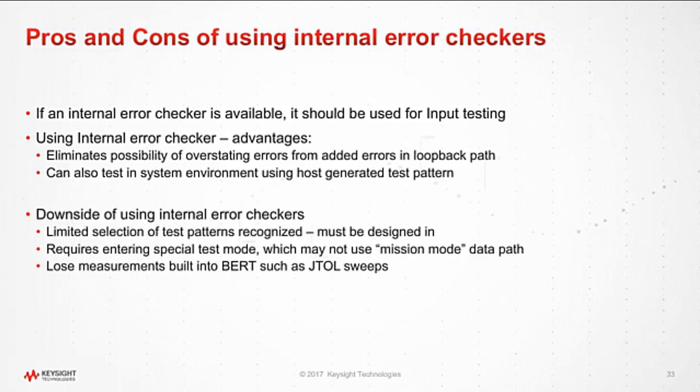But what are the downsides? Well, the biggest downside is that you're limited on the selection of test patterns that you can use. You have to design the error checker into silicon when you design the chip, and many of them allow more than one pattern to be used, which is useful. But maybe you want to test with a specific pattern because you're looking for a pattern sensitivity or something like that.